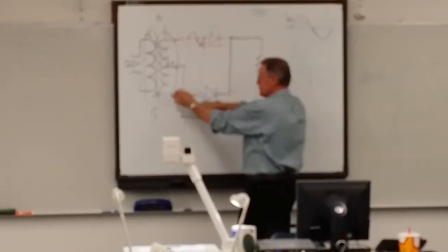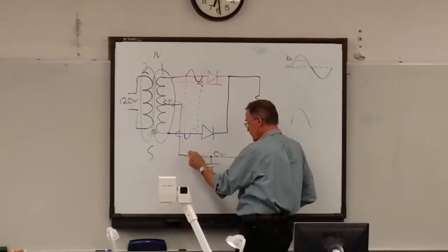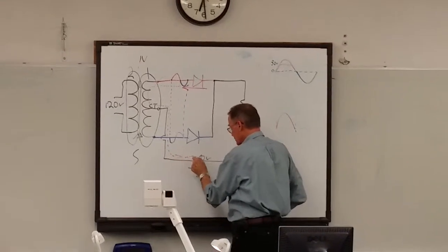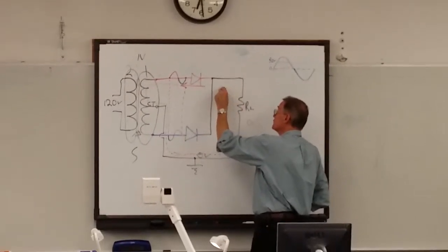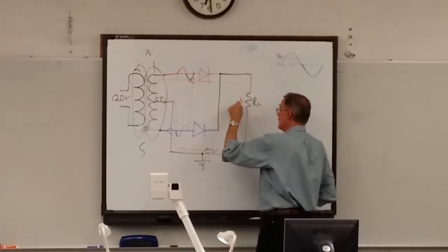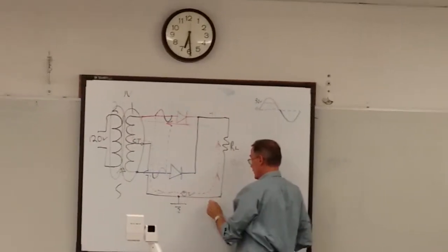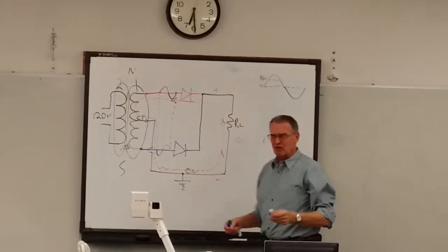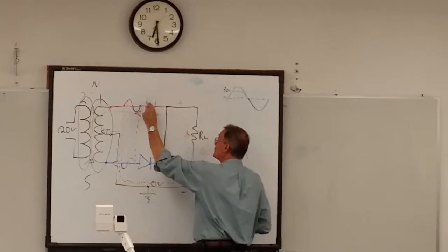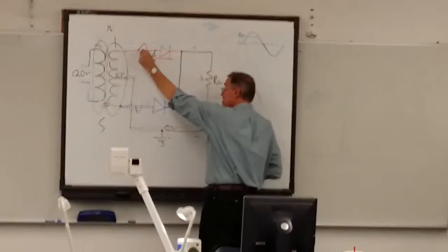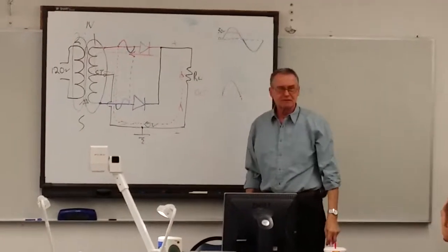So that's an open circuit, so the current is forced, and we're going in this direction, notice. We're flowing negative to positive, and the current's flowing up through that diode. This is positive, and that's negative. Now, how do I know that's positive for sure? By looking here. That diode, when it's on, is a direct short. And that's all during the positive half. That means that has to be positive.